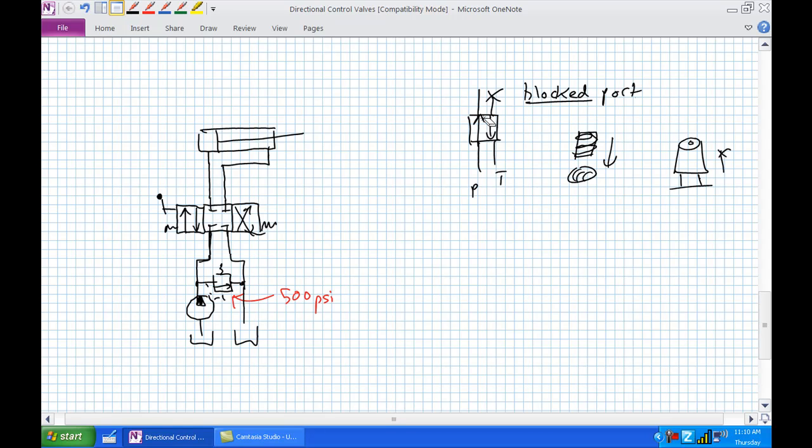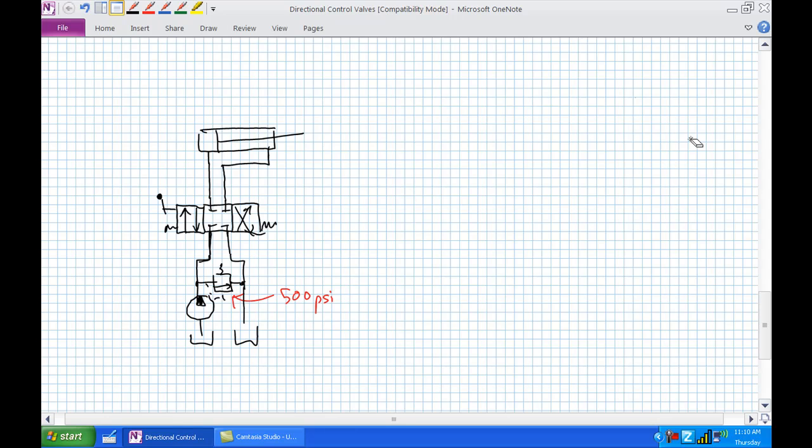What was I talking about? Oh, we're talking about the center position here. What happens in a closed center position? Obviously, the pressure relief valve is constantly being activated when it's in the center position. And anytime that the straight through condition has extended the cylinder fully and it's reached the limits of its travel, again, it becomes a closed path. Or it's in the cross connect condition and it's retracted itself fully and it becomes a closed path. That pressure relief valve has to activate.